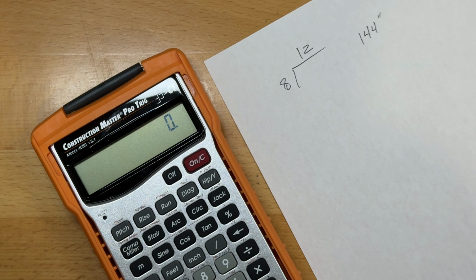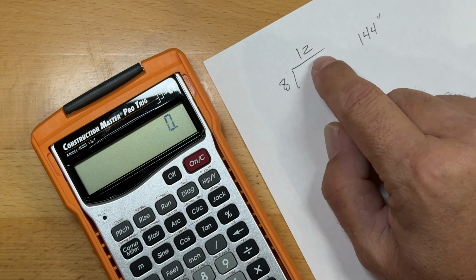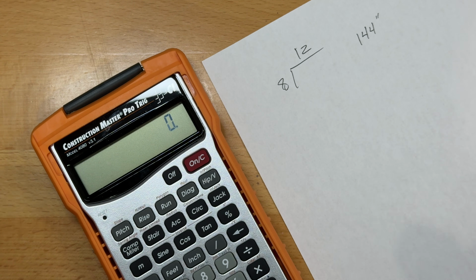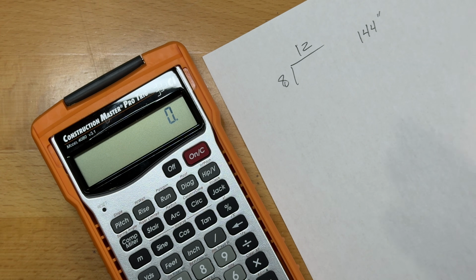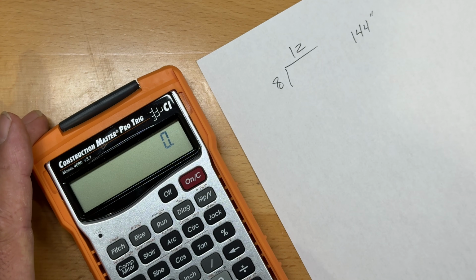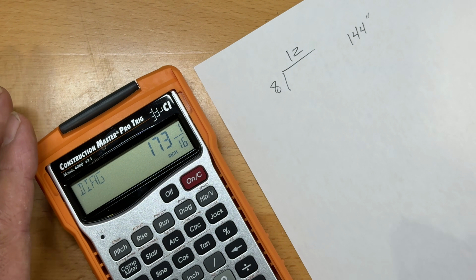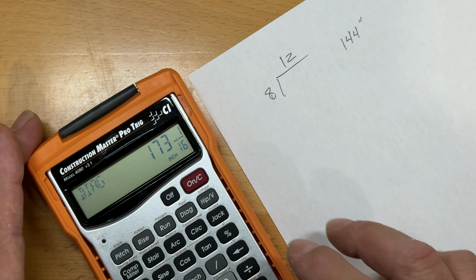Okay, so in our example roof, we're going to say that the pitch of the roof is an 8/12 pitch, and for brevity's sake, we're just going to say it's an even 12 foot. And let's clear the calculator first so we make sure that we don't get any bad inputs. The way we input this into the calculator is like this: 8-inch pitch, I'm going to put it in inches, 144-inch run. Then we can hit the diagonal, and that is going to tell us the length of the common rafter, in this case 173 and 1/16.